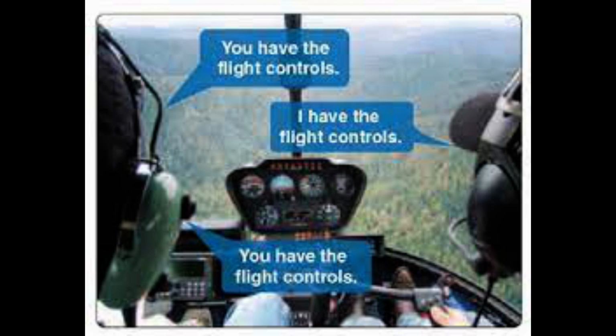This is determined by reading the FD's command bars. If the commands shown agree with your perception of the control motions to be made, then engage the autopilot to fly the entered course in vertical mode. A caution at this point: some FDs cancel the altitude hold mode when the autopilot is engaged. Always ensure that, after autopilot engagement, the desired modes are still active.